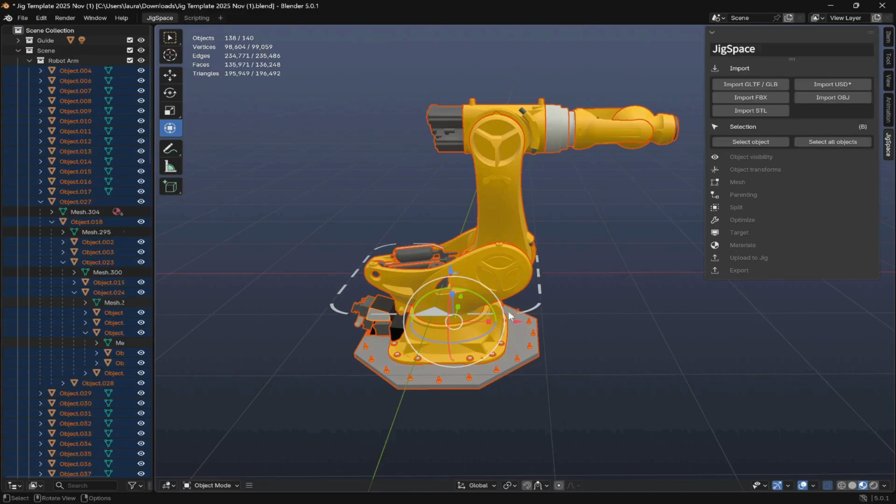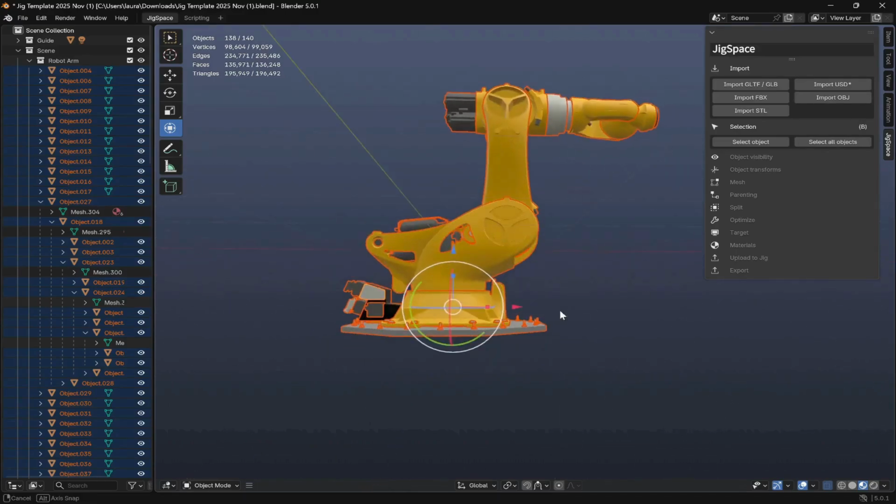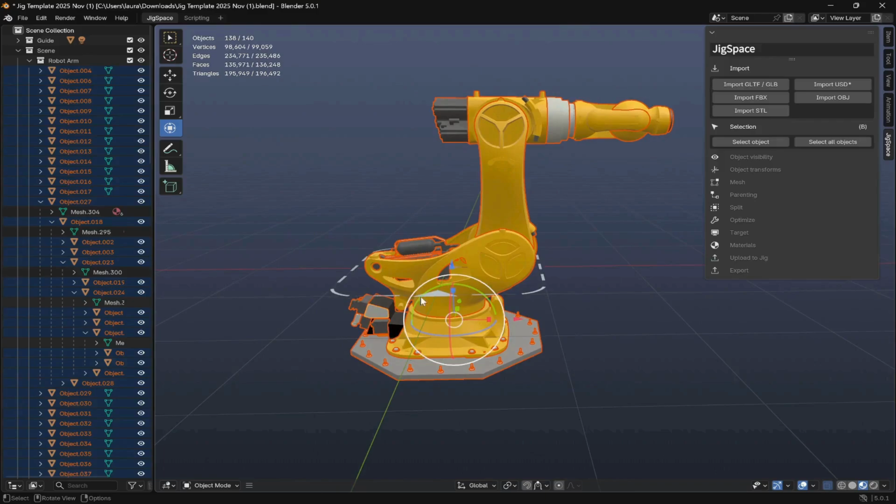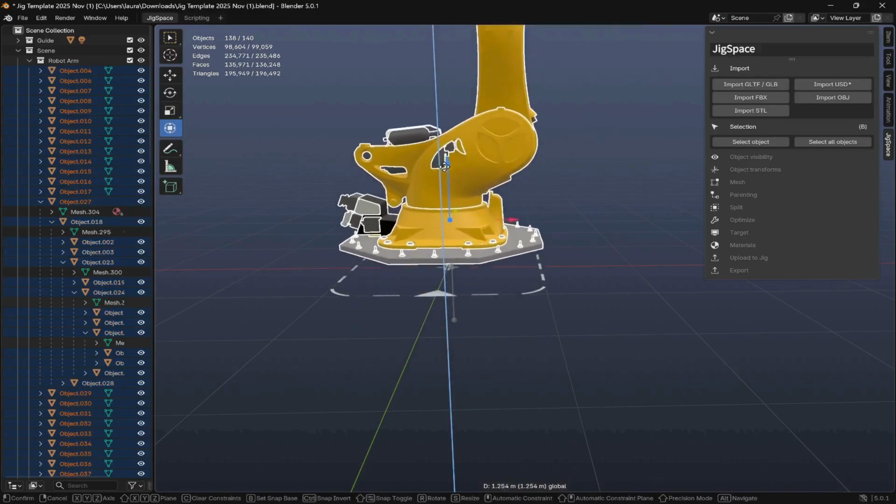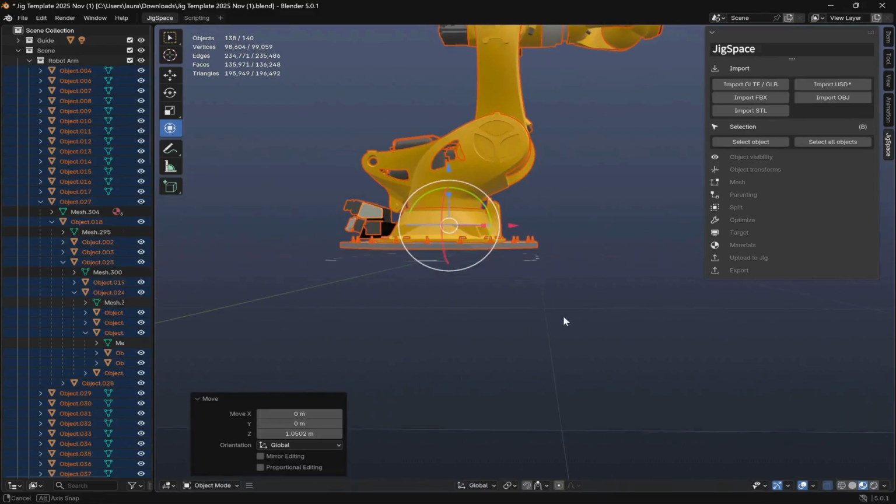Now what I'd like to do is lift up my model and position it so it's sitting just on top of this floor here. Now I can do this by clicking and dragging on this gizmo. I'm able to move my 3D model using the Move tool, rotate my 3D model using the Rotate tool, and scale my 3D model. But we also have this multi-tool available, so I could click and drag on that blue arrow to try and position my model right above that floor here.